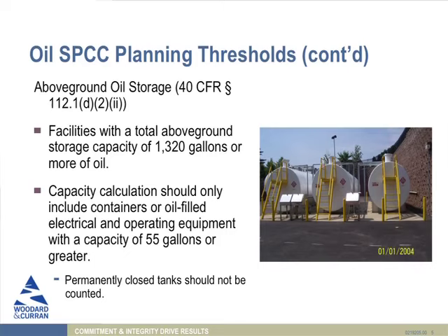The exception to this is if you mean an oil water separator to act as your secondary containment for some sort of bulk oil storage tank, then it is covered under this program and would be subject to all sorts of inspection requirements and that sort of thing. We typically wouldn't recommend that. Say you have a garage area where you're storing 55-gallon drums of oil and they need some secondary containment. If you say, well, the oil water separator in the floor drain is my secondary containment, then that oil water separator is now in the program, subject to the rules, needs to be inspected and everything else.